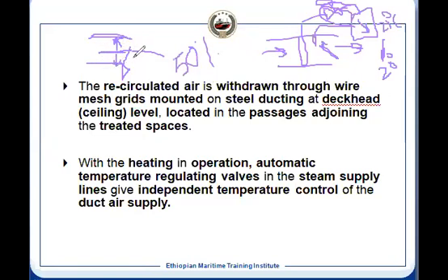So that allowance we have to adjust. But if it is fully closed, you will be able to adjust. That is the reason 50% is the best position, but it might not be 50%, it may be 60%. Like take us at 75%. 75% will be at the higher side. So around 60 to 70% it may be. Even at 75% you still have 25% to adjust if the temperature is less.